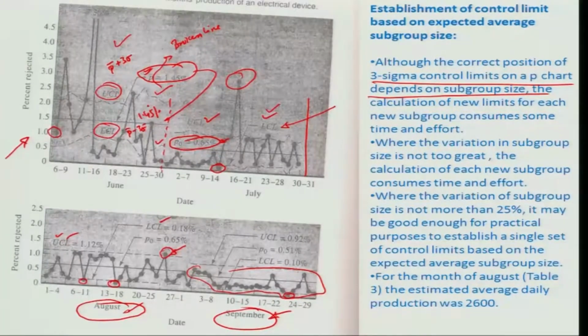Okay, so this is how you try to control your quality based on the various aspects of the P control chart. Because it is attribute related, you need not quantify; you can just consider a piece to be rejected or accepted, and it gives you a lot more flexibility than the X chart or R chart, where you can only mention one characteristic dimension based on which you plot the X and R chart. So, this is Shewhart's acceptance sampling based attribute control chart.